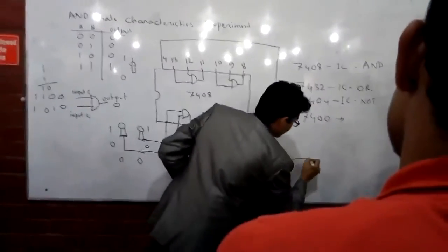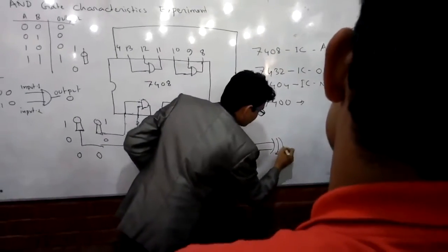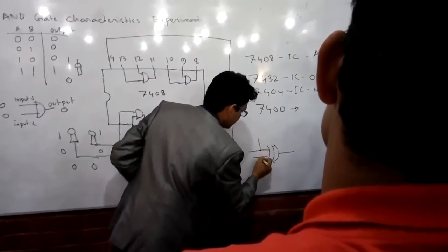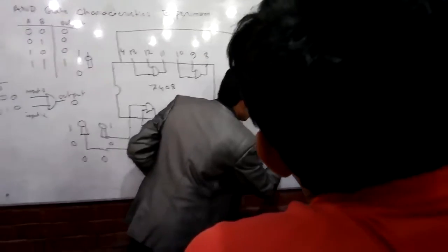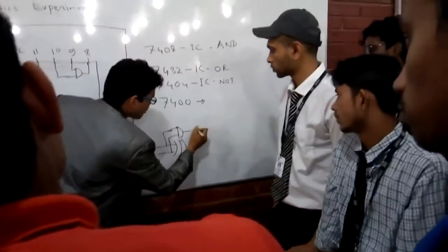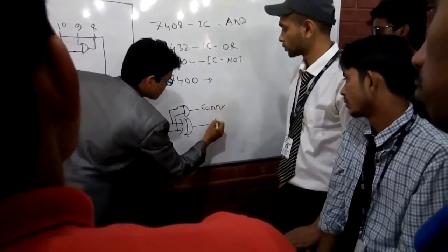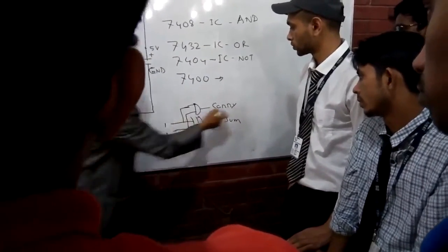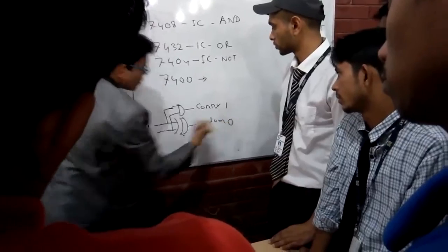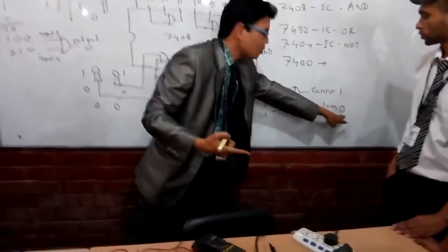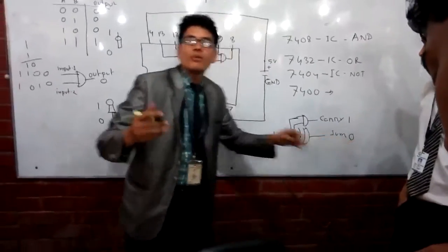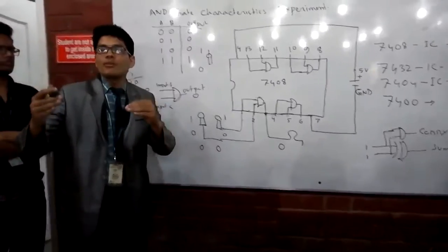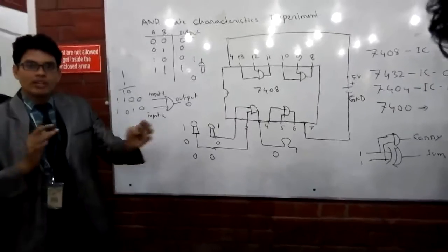Listen, in an adder circuit there is an XOR and an AND gate. These two together make this one stand for carry and this one stand for sum. So if we give 1 and 1 as input, carry will be 1, sum will be 0. So the light for the AND gate will switch on and this will be switched off. That is how the calculating parts of the arithmetic logic unit of a computer are made.